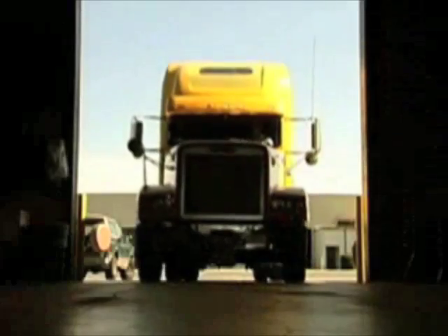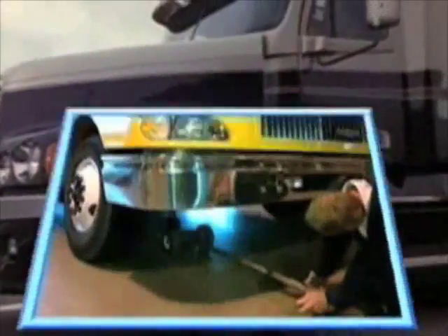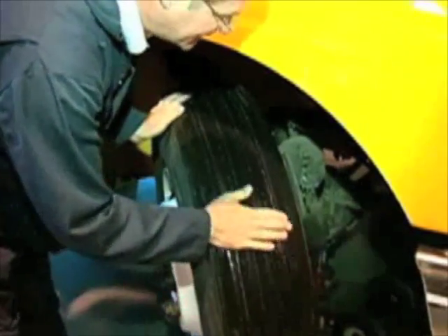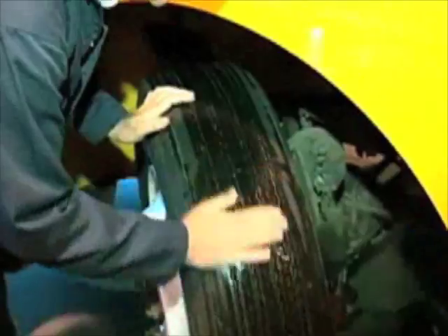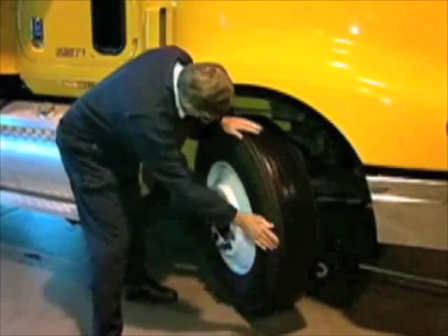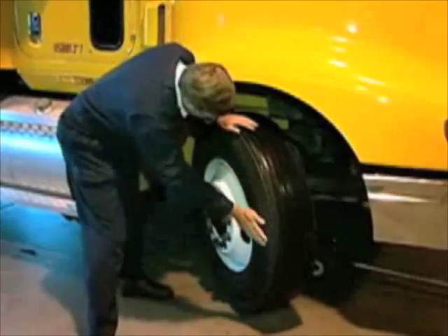Bring the vehicle into a work area. Since the initial complaint was felt in the steering wheel, we will conduct our investigation on the steering axle tires. We will need to jack up the front axle. Rotate the tire assembly and inspect the tread area for any large cuts, objects in the tire, or tire wear abnormalities. Also, while rotating, check for any grabbing brakes or any obvious tire balance irregularities.